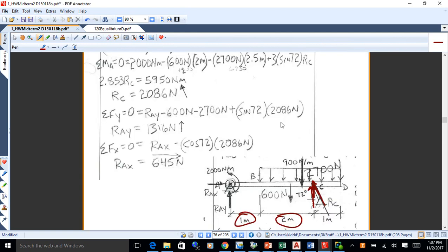So it's really important to get a good free body diagram. If you get that, everything just kind of falls out. If you understand the basic approach and get yourself a good force diagram drawn up that's dimensioned and ready to go, you're good then. You can just do a moment and then do force equations. That's about it, okay?